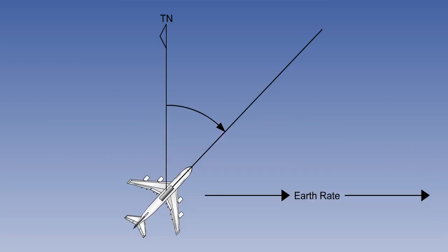Once the system has been correctly levelled and earth rate corrections for the correct latitude applied, any remaining error can only come from incorrect alignment with true north. By analysing the residual forces, the computer's axis transformation system can establish the direction of the Earth's spin and therefore find true north.